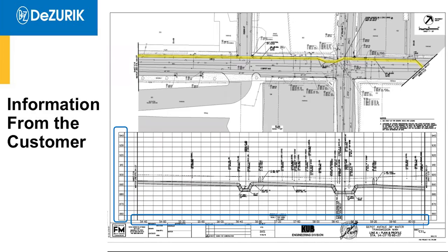There's also some low points and high points. And those points are what matter to us. So the first thing we would do is look at this and record the high points. And yes, probably a pencil and paper is the right way to do it. But look at 5440, or just to the left of it, probably 5420. And at that point, 5420, your elevation is 895 feet. So you move on to the next point.